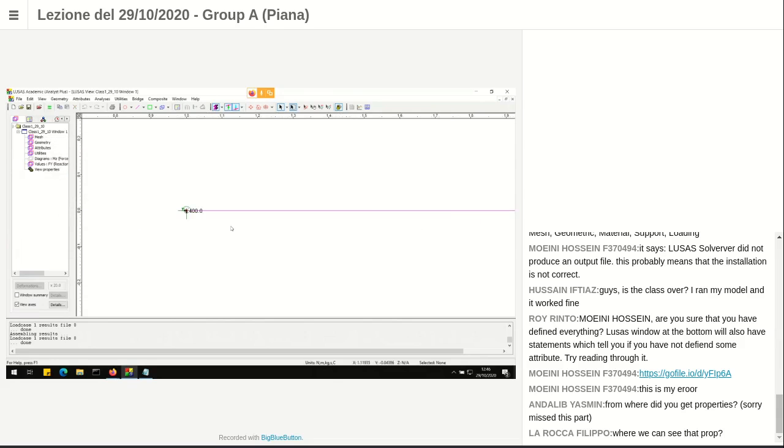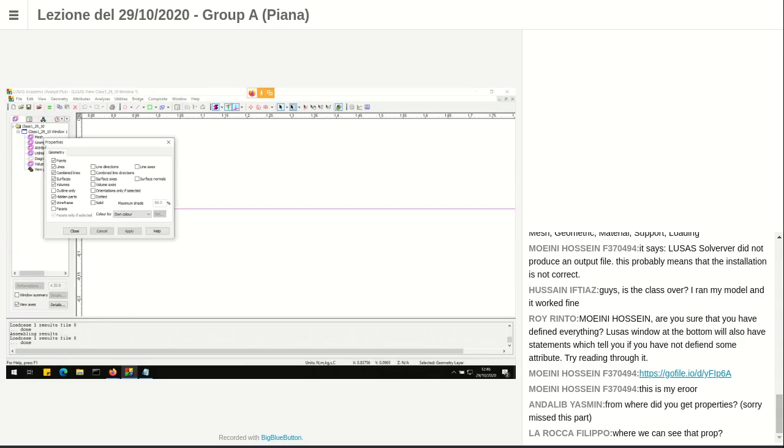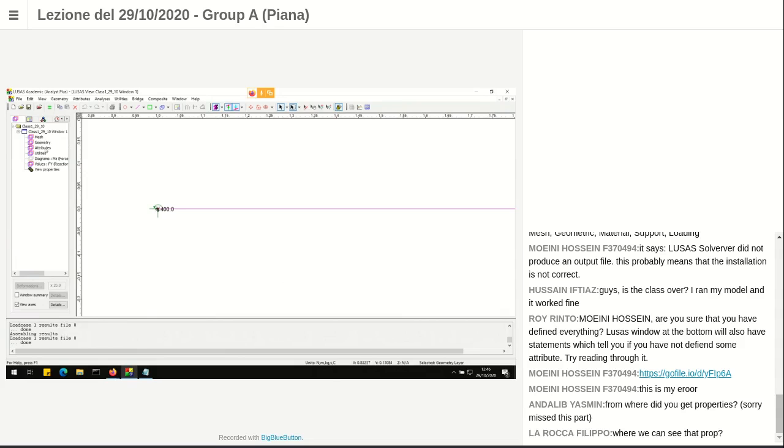As you can see in vertical direction, here if you don't want to see the green reactions at the beginning, you can go left on layers, geometry, I'm wrong, it is not here, it is on attributes, sorry, so layers on the left, attributes, support, and deselect, so I click none, for example, okay, so they disappeared, and only the value of reaction that you selected is visible.